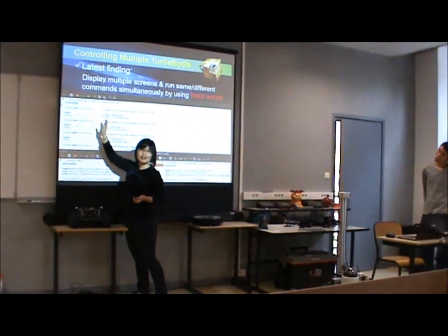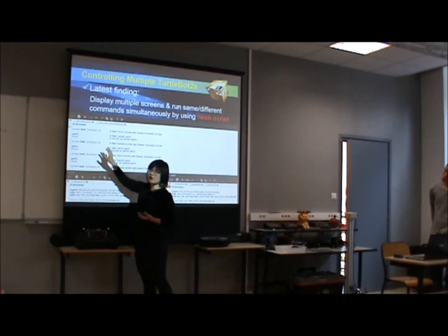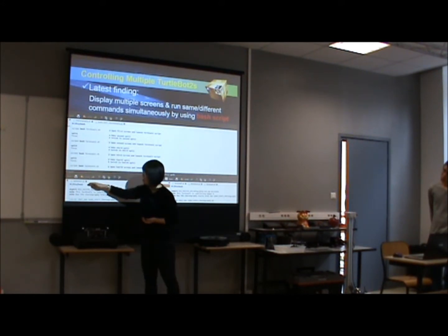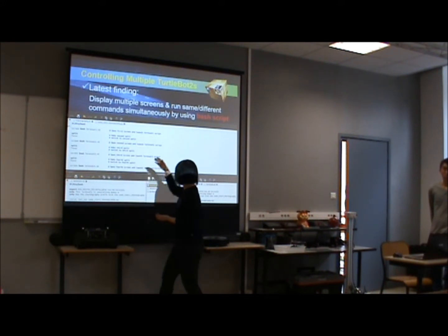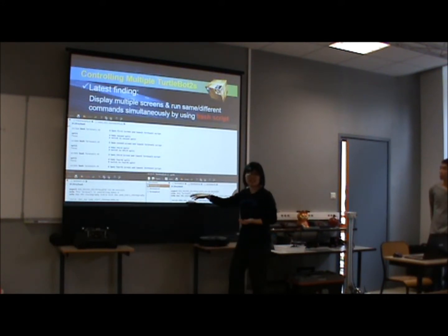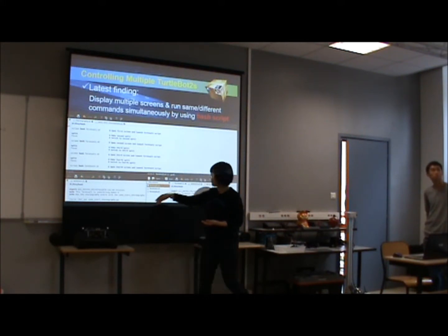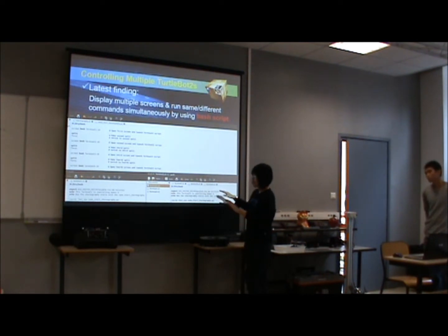Okay, basically when we want to run the choreography, we only type in the terminal bash choreography.sh, and in this bash script, it will automatically run other bash scripts, which means in terminal 1 all the commands that I want to run, and in terminal 2 also the same commands. In each terminal, I give the IP address of each TurtleBot, and inside that, let's say here I'm running the command start choreography. Here also I'm running the same start choreography, so that it will move simultaneously.